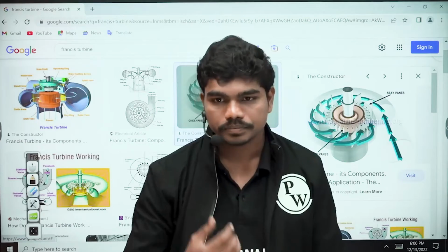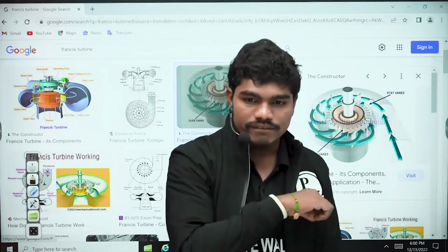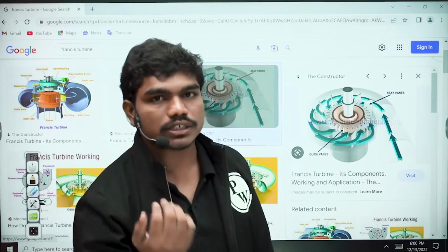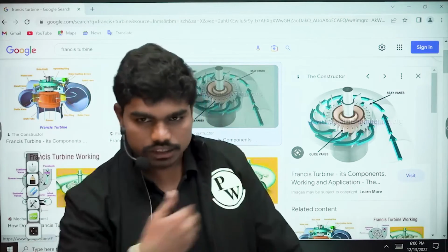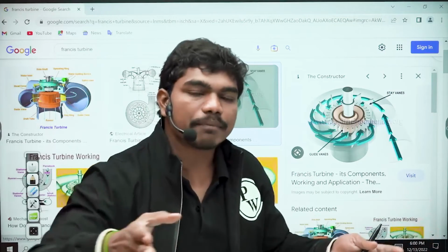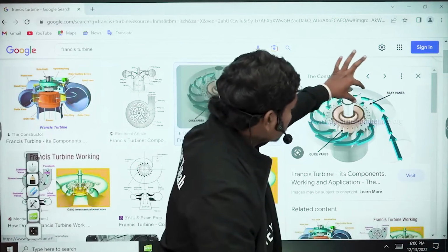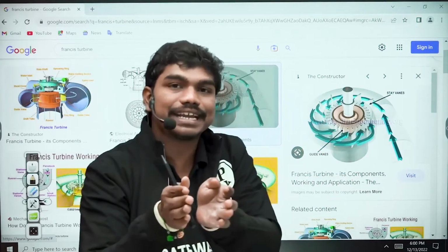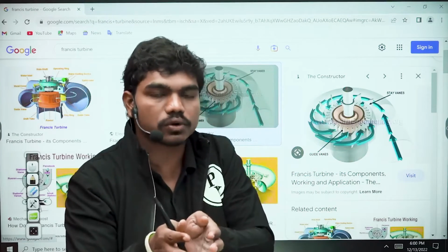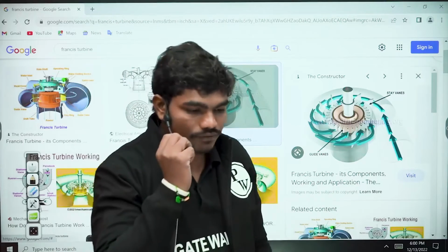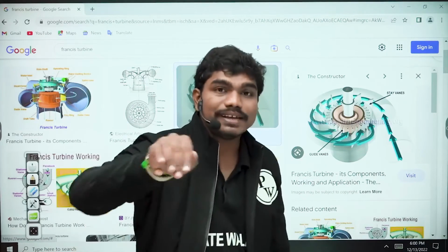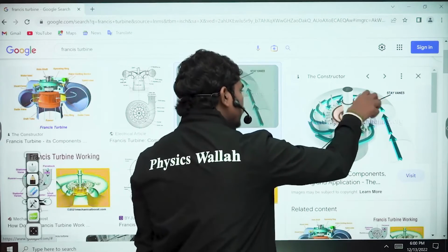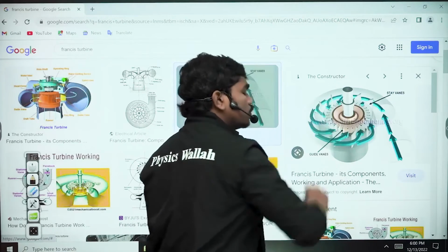So when the discharge is decreasing along the path, to maintain the same velocity, instead of putting a circular tube you will have a slightly tapered one, so that as you come towards this location the cross section of the flow decreases. You might observe this in your labs next time you go to a hydraulic machines lab. In the case of a Francis turbine, the casing will be spiral, not circular, which reduces the flow area in this direction.